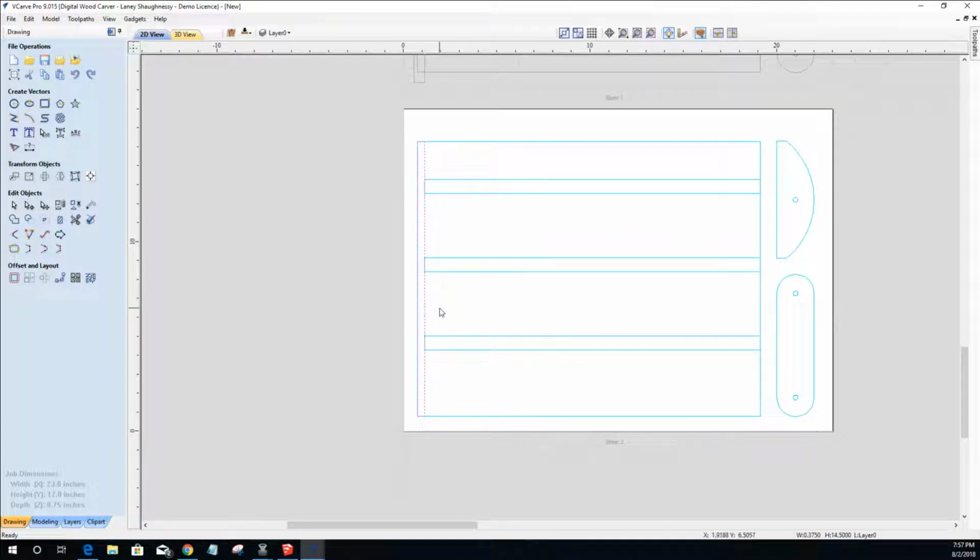Okay, so now let's go ahead and extend one more time, and this time, since they're all 3 getting extended the same, I'm just gonna hold down my shift key and select all 3 of these, and that way I can extend them all at the same time instead of doing them individually. So just bring those out like that. We'll select on this one, let go of the shift key, pull this one side out, then hold the shift key and pull both ends together out a little bit like that. And now we're ready to create the toolpath for sheet 2.